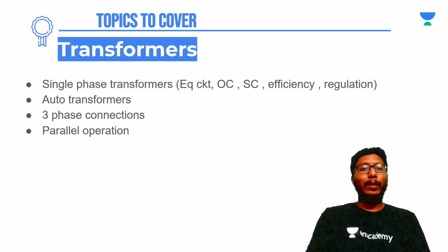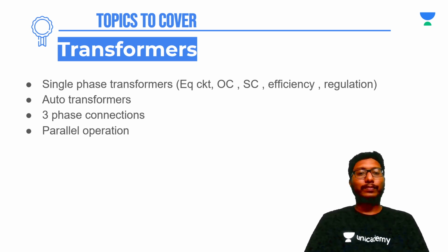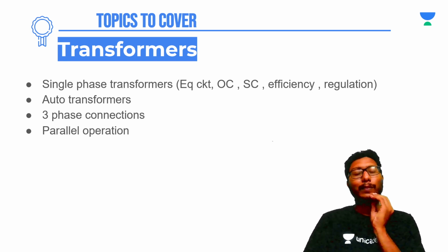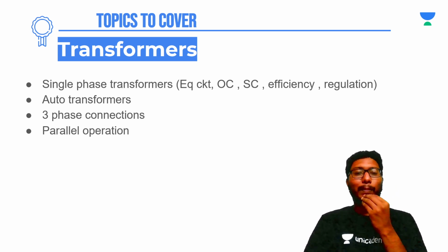And another problem is, you will be given in the problem statement that the transformer has the same efficiency at two different loads. From that you have to calculate the maximum efficiency, or the load at which maximum efficiency is occurring. So that is again another type of problem. And also from this type of problems, you might be asked to find out the percentage impedance or percentage resistance or percentage inductance of the transformer. This you can be asked, and also no load parameters might be asked.